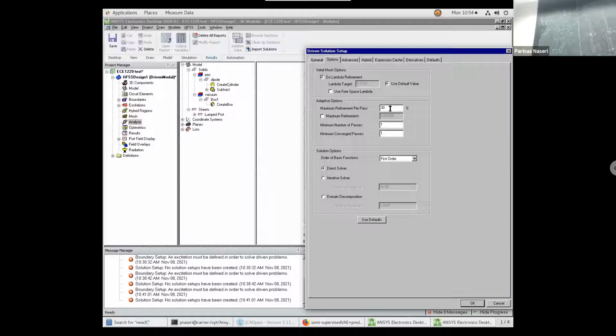You will leave one of them as it is, the other one divides it to 2. Now, if you mention you can go to, I don't know, like 70%. Then the second pass, it tries to go to number of cells, four mesh cells. Now, what does that mean? That means that the difference is this. You had in pass 2, you either solve for 1, 2, 3 mesh cells or 1, 2, 3, 4 mesh